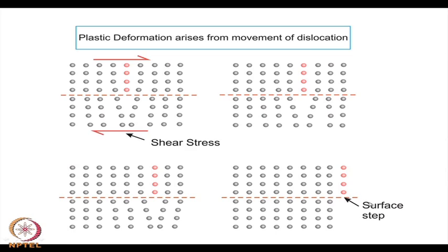So, if you apply temperature, you are supplying an activation energy. That stress likes to be released, so the dislocation starts moving, and as the dislocation goes out of the crystal, the stress is released, okay, because it is at the expense of forming a step. It is generating a deformation, resulting in a physical deformation. So, as more and more physical deformation takes place, the dislocation density may be reduced.